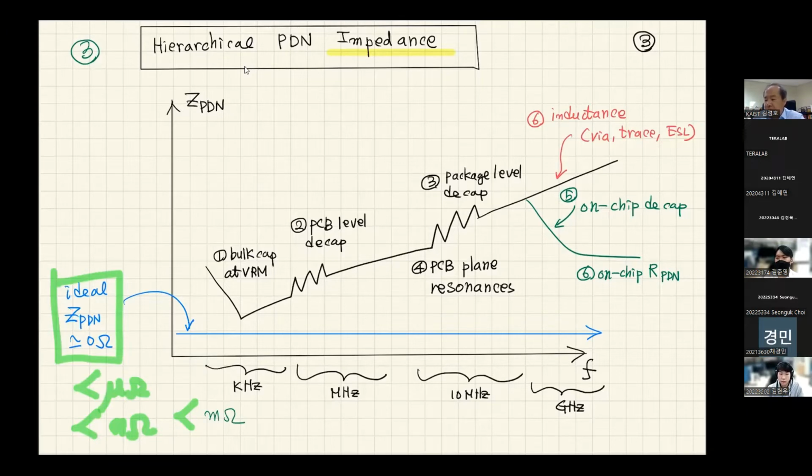So this is very unnatural, but what I'm saying is that our target impedance of the power distribution network is a very small impedance from DC to gigahertz, or later on even 100 gigahertz. So very broad.